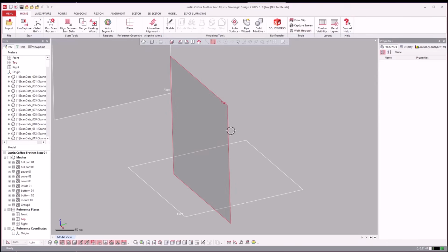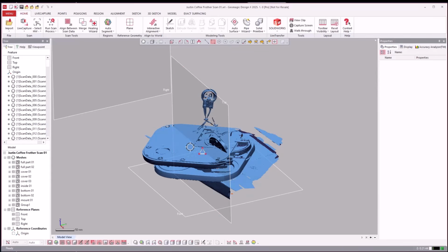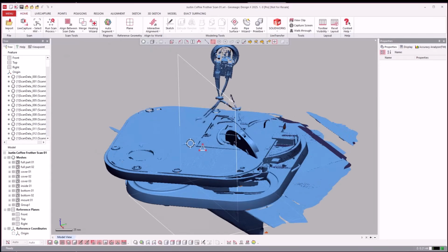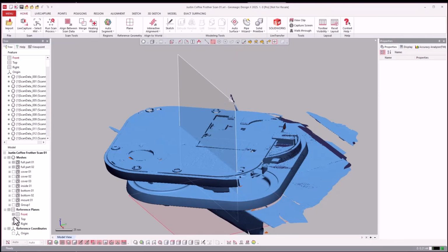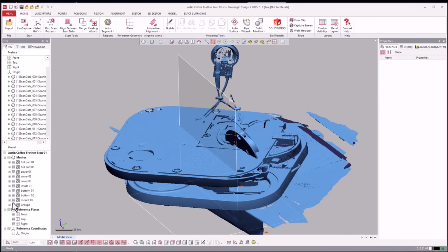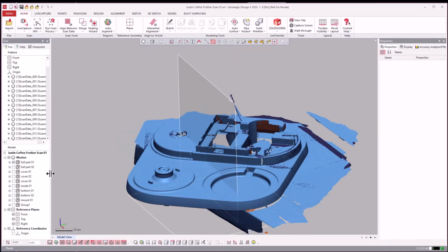So now that I have all of the scans, I'll show you everything here. Turn them all on. I didn't show every one in the video, I just showed scanning certain parts. So let's go over them first, and then we will take it from there. I'll just click and drag down on the eyeballs. By the way, that is a shortcut I've explained a few times here, and it's an awesome shortcut trick inside of Design X. If I click and hold and drag up and down the eyeballs, you'll see how it turns them on and off.